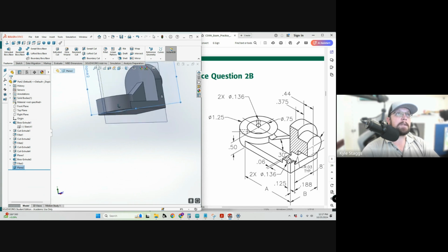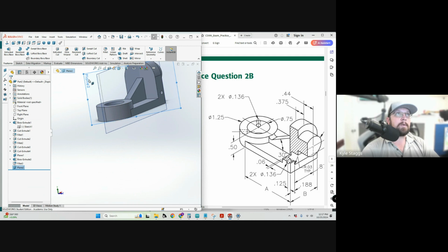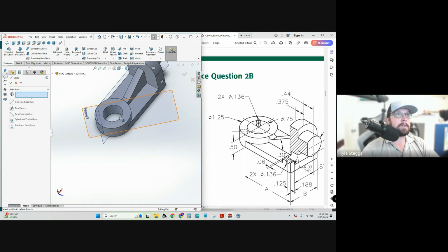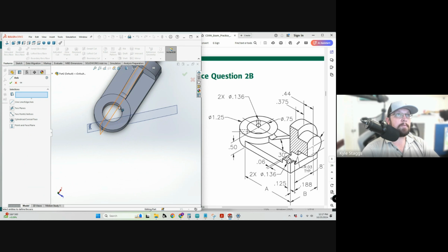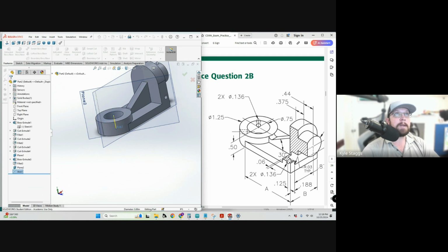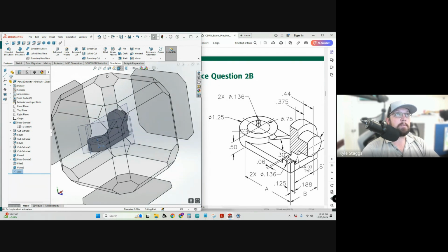But what I have to do is line that up with the center line. So on plane 2, I have to select it. I have to add a sketch. And then we're going to have to do another reference actually to be able to use it, called an axis. So stuff that you generally don't have to deal with, but we're going to use this cylinder and drop an axis through that. Okay. I'm going to change the view so that we are square with respect to the plane.